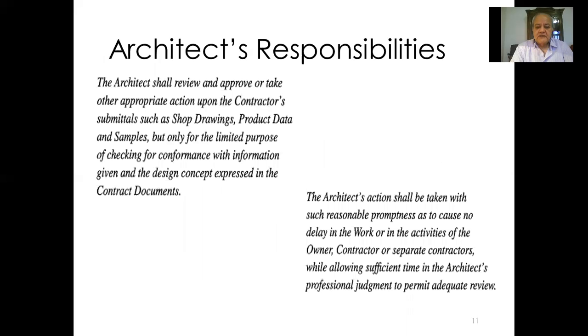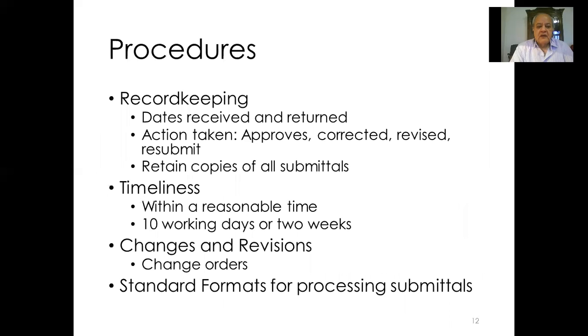So the drawings are sent back to the contractor, approved, with any samples, any data, and make sure that they follow the contract documents. This is your main role, is to follow the contract documents, the working drawings, the specifications, the quantities, the colors, the strength of the material, the size, and so forth. So the procedure is to receive the data from the contractor. So you have to have good records.